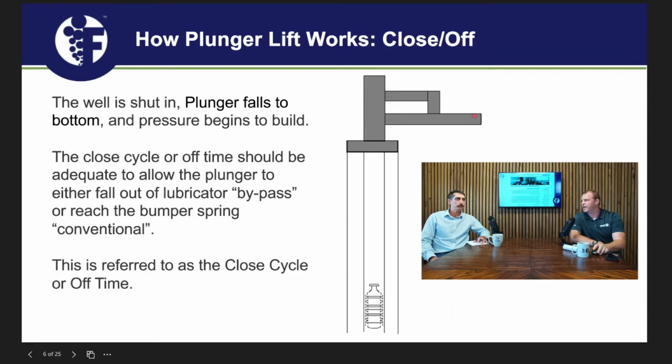And that supply gas that's used to control that can come from where, the casing, separator? Wherever you have dry gas, it's really important that it's dry gas. Dry gas, okay. If you pull it off the flow line somewhere or off of a wet supply, you can cause either the electronics in the box to malfunction or the latching valve in there or something to go out. Gotcha, because of those liquids in the gas.